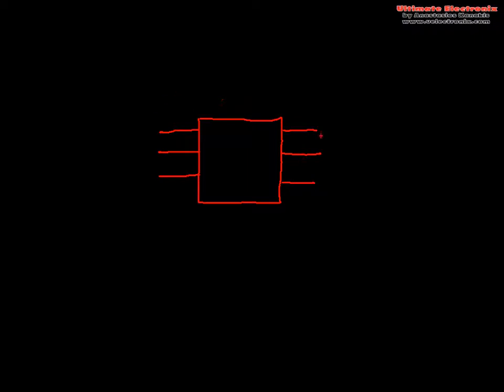For example, when we press a button, for example, this is one button which will connect to this pin, and the other pin will be connected to the ground. So when we make this connection, this pin will be touched to ground. When we do that, we want, for example, to turn on a light from this pin.